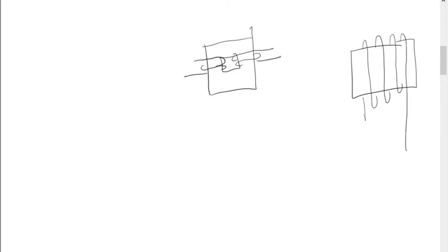So what happens in a solenoid is, remember Lenz's law? What happened in Lenz's law? If you take a magnet with a north pole, and it approaches this soft iron core which is wrapped with copper wire, as long as the magnet is moving, you get a change in flux, right? Which leads to an induced EMF. Induced EMF may lead to an induced current, right? So we start off with EMF and then current. Acha, a couple of quick questions. What's going to happen if I move this faster? The change in flux will be more, right? And what's going to happen if I increase the number of turns here? Same, right? It's going to increase the EMF.